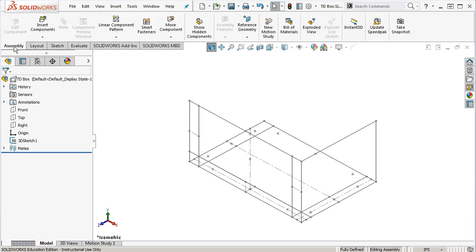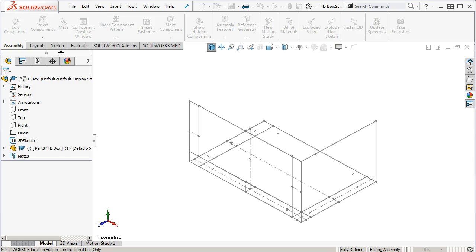Where we were in the part, we were creating a solid body. Now I'm going to insert a component and tell it that I'm making a new part. In bottom up, we just brought in insert components, and it just kind of rolled with that. When I tell this to make a new part, however, it's going to ask me for a sketch location. By default, it's the front plane. Well, I don't always know that I want it to be the front plane.